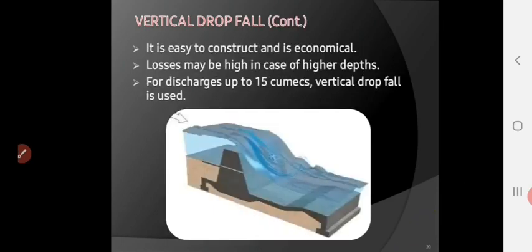This is the vertical drop fall sketch. It is easy to construct and it is economical. Losses may be high in case of higher height or depth. For discharge up to 15 cumecs, vertical drop fall is used.